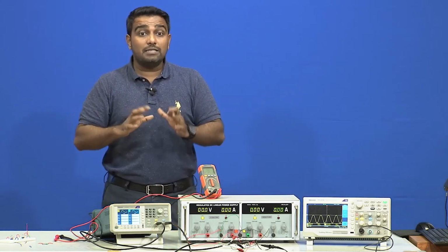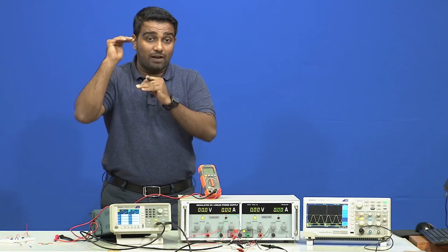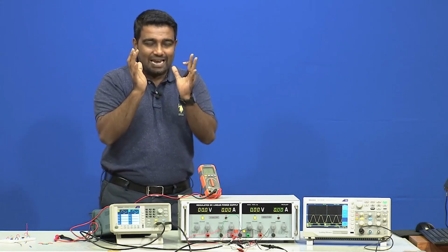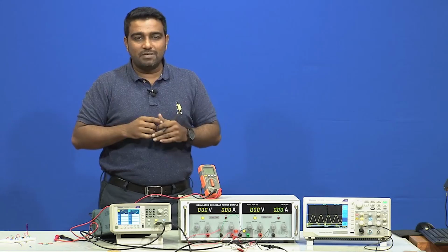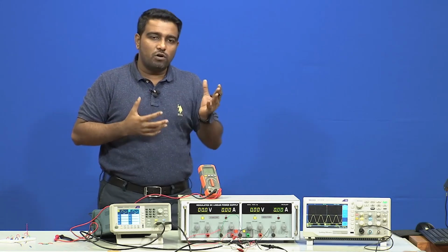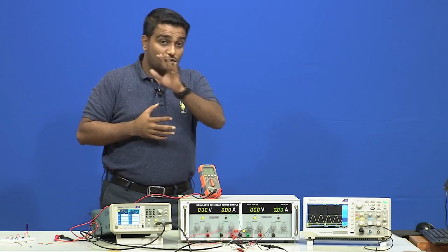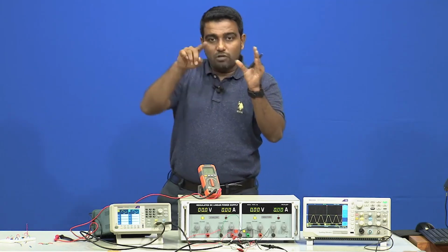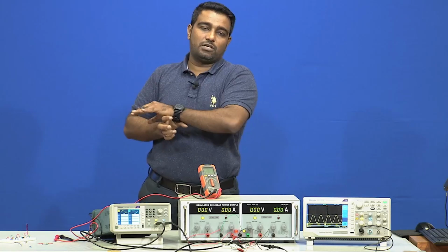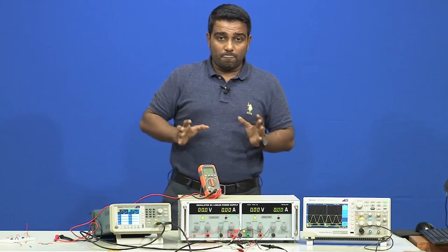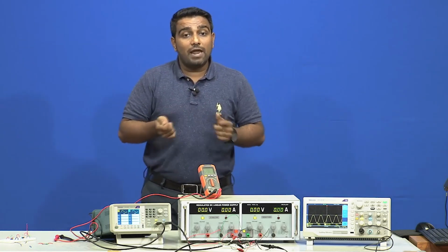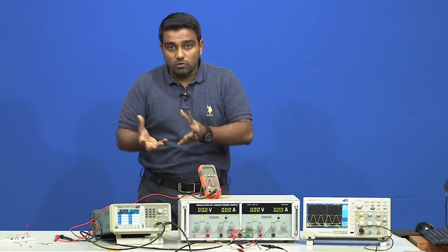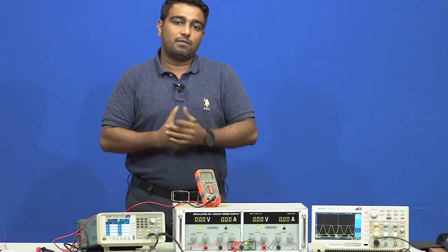But it is an amplifier also, that means it will amplify with the gain that you have set. That means if your gain is about 2, sorry, it should never be volts, gain is about 2, then 2 into the sum of the input signals, very easy, right. This is how you can use the operational amplifier as a summing circuit.